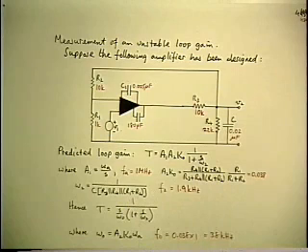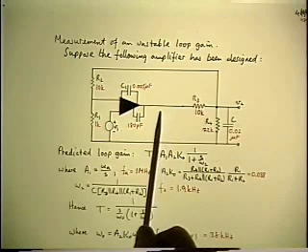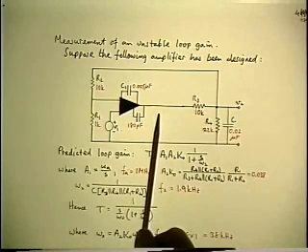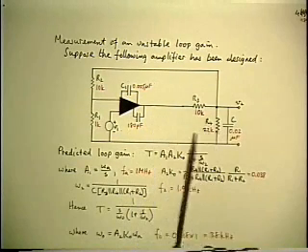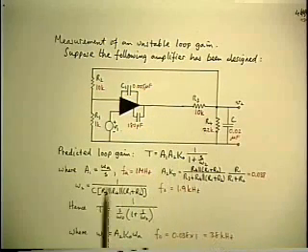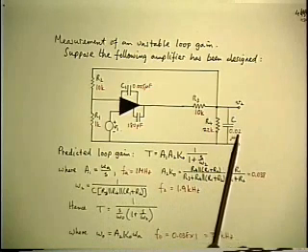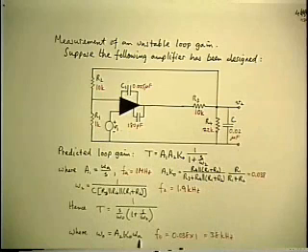Remember, just to review how we did it, we chose an injection point at the output of the op-amp, did series voltage injection, split the loop gain into 3 factors, calculate them separately using the extra element theorem to restore the capacitor after leaving it out at first.